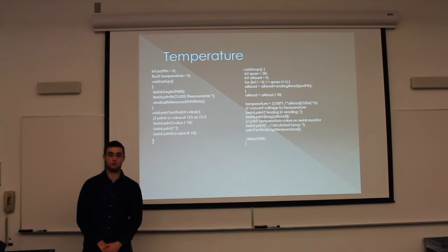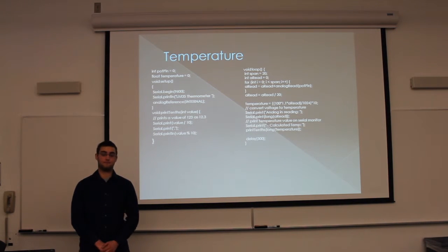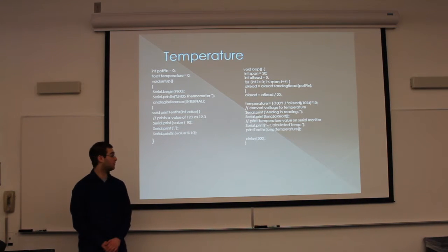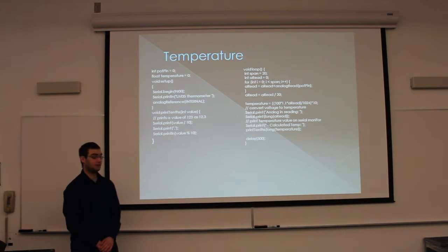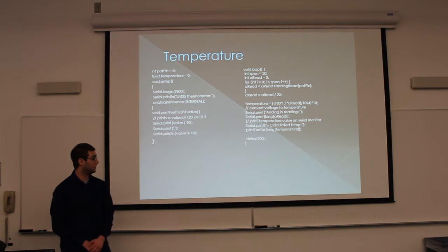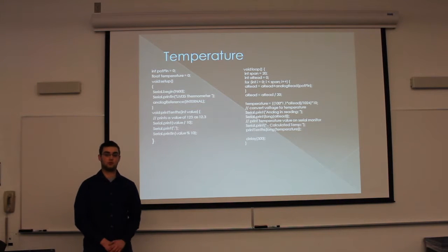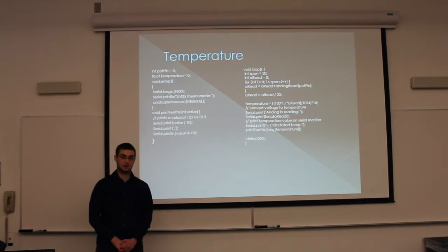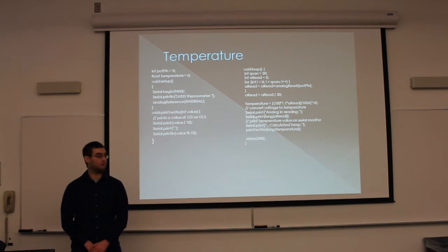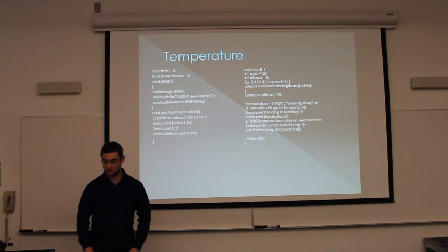There's a different time, for the light sensor, where you'll see that the conversion actually has to be made by hand. So this one isn't too bad. And then the last part of the void is the calculated temp. What it'll read in the serial port is the calculated temp, and then it'll say what the calculated temp is in degrees Celsius. The delay of 500 milliseconds is so that it doesn't completely fill up your screen immediately. It gives a half second delay between each time it reads the temperature, which is still fairly fast, but it does give a little time for change.